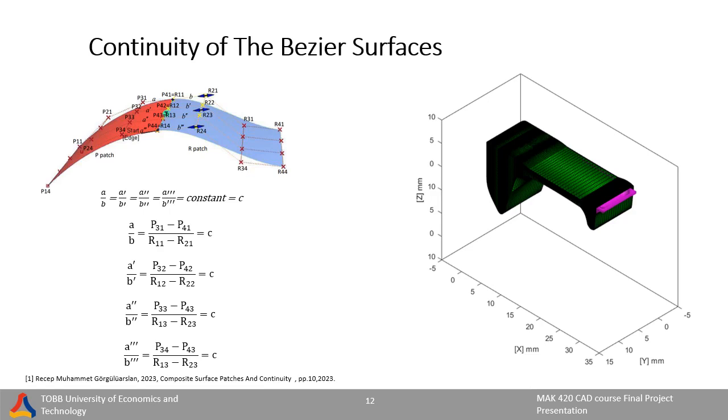There were some gaps in the model resulting from topology optimization. Normally, the upper surface of the gun grip is in contact with the gun to ensure that it is attached to it. In order to ensure sufficient contact and fit of the gun grip to the gun, the volumetric spaces can be neglected. In addition, there is an extension at the end of the model. Since gun grip models generally do not have such an extension, it is thought that this part is not needed. As a result, this part was also neglected in surface modeling.